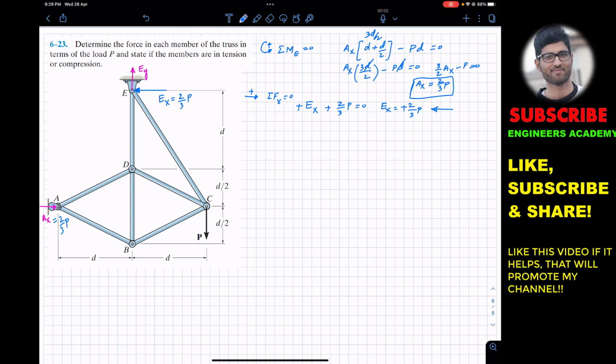And similarly, if I apply the summation of forces along Y, that must be equals to 0, where the upward direction is our positive Y direction. So now we can say that EY is acting in the positive Y, so plus EY minus the external force in the downward direction, so minus P equals to 0, and EY is equal to P. So EY is acting in the positive Y direction. This is EX. Now let me write that EY is equal to P.